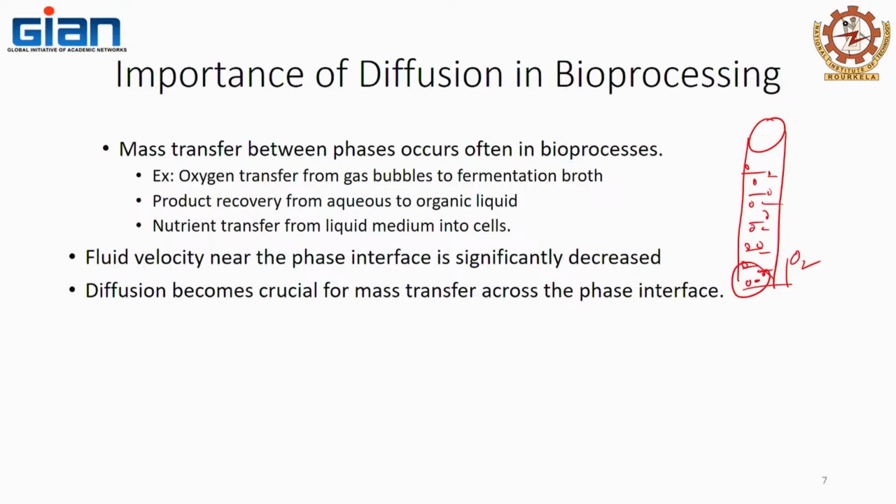If you have a fish tank at home or an aquarium, close your eyes, remember how the bubble is moving up in the aquarium. Does it remain the same size, or increase in size, or decrease in size? It increases in size as it goes up, right? Why? Because the pressure keeps decreasing with the depth, and by the moment it has touched the top, it has become bigger. Now, oxygen transfer from gas bubbles to the fermentation broth will also follow the same principle. That's why when you are sparging oxygen, the design of the sparger plays a very, very important role.